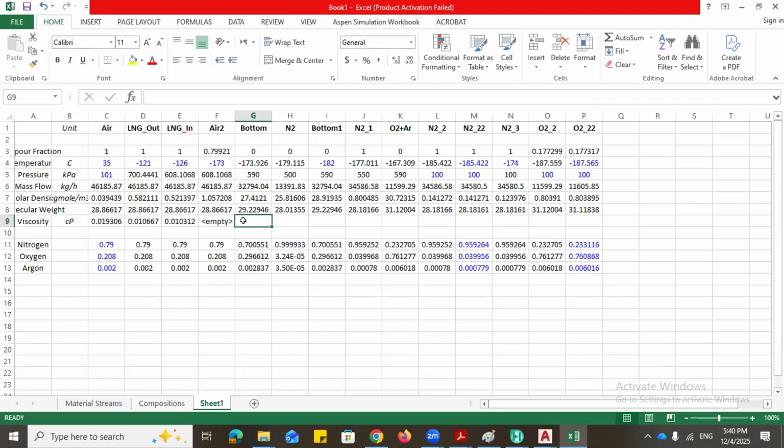So let me start with this. This is the heat and material balance, HMB. This document contains process conditions which we get from our simulation. So these are the process conditions. Whenever you want to size a line, you need temperature, you need pressure, you need the flow rate, you need the density, you need the molecular weight, you need the viscosity. When you are sizing a line, you don't need the conditions or the compositions. You don't need all this. But when we are generating our heat and material balance, we always present it like this.